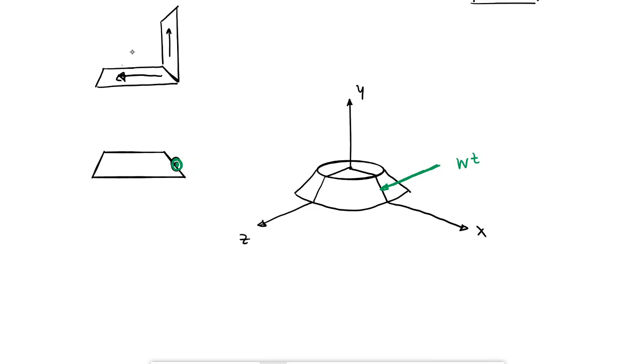WT. That is what's making it rotate. That's causing the torque, and this is what I can calculate from what I said before. I have torque that is equal to power over omega, but that is at the same time the tangential force times the radius of the gear. This is what I can figure out in terms of everything else. So that's why that is the most important one.